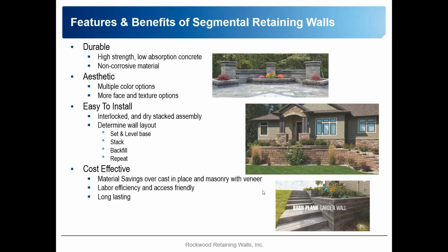Where is that grade separation that you need, and what are you trying to outline or to either hold back or hold up? Get your wall layout, get a good level, set and level your base, stack it, backfill it, and repeat that process. So very, very easy in the field.